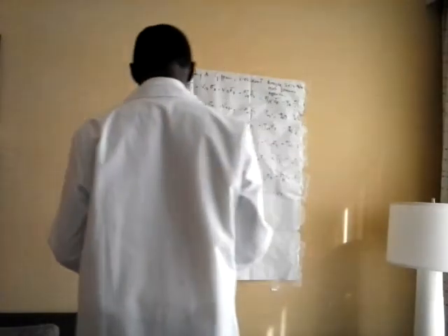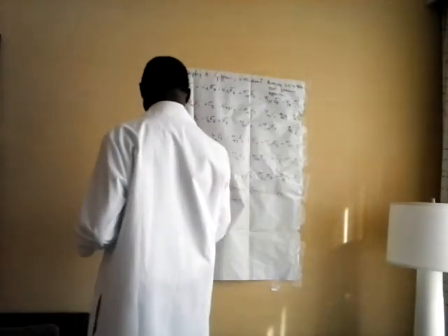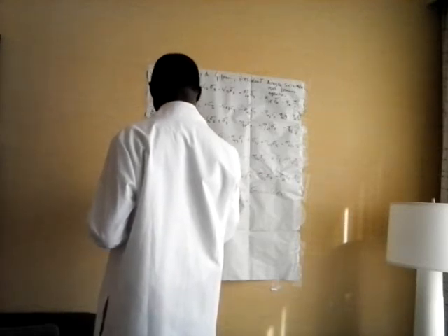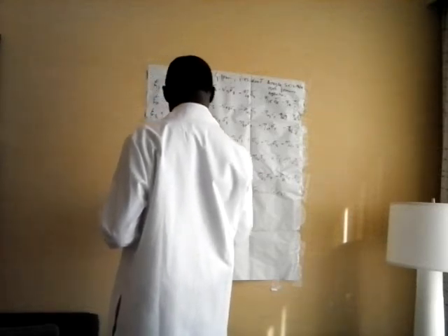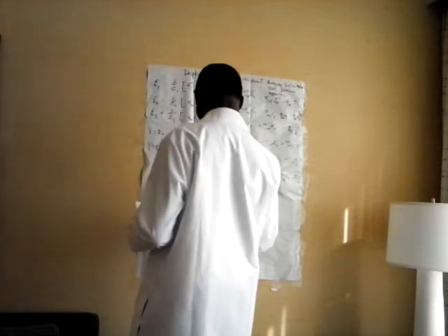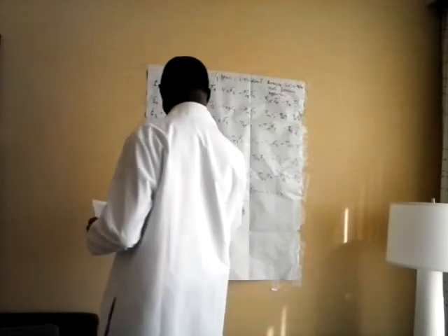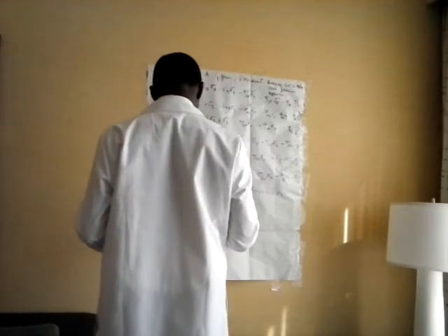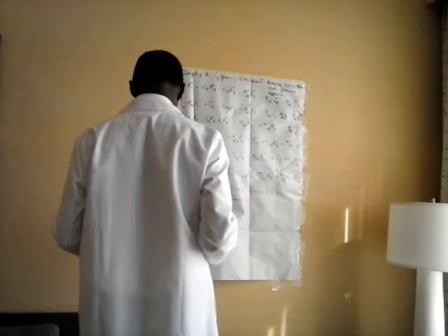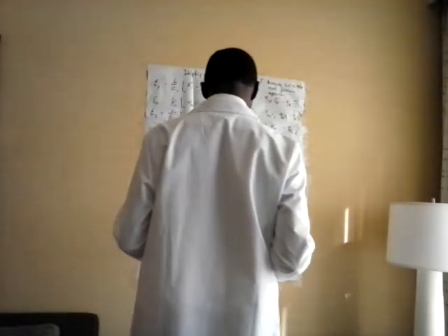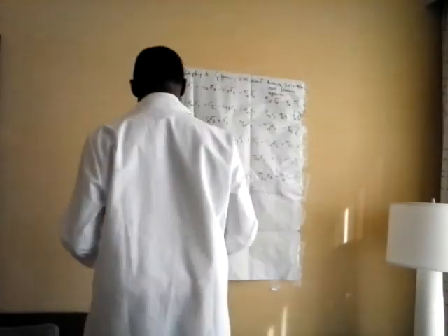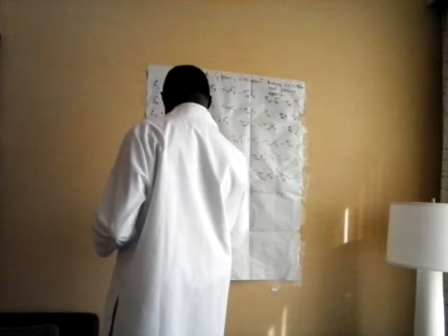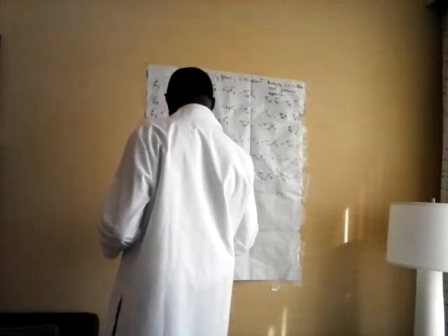Take for example the orthotropic case once more here. In the material principal axis, there is no coupling between the extension and the shear, and no coupling between the planes or the shear, so that all those terms equal 0.